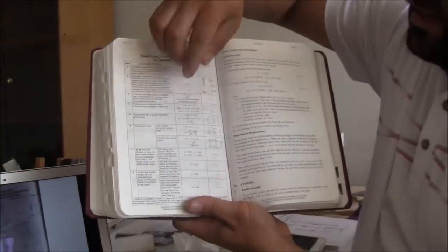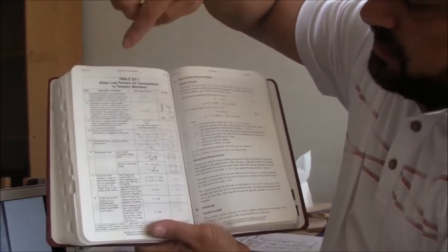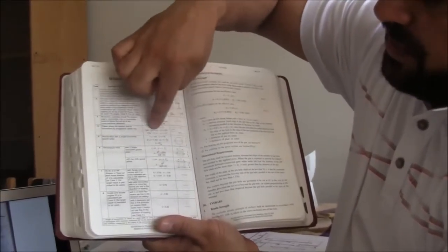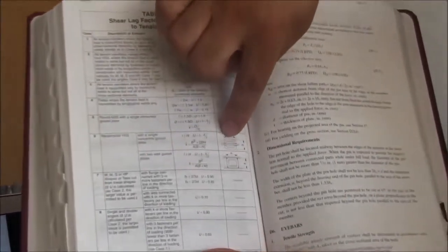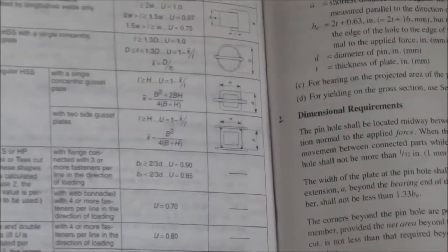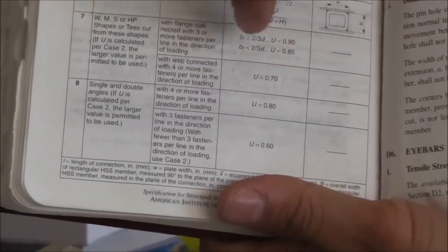This includes all the cases, and it includes cases for the welded connections. This is for the welded connections. And this is for the HSS cases, hollow steel section. It could be a rectangle, it could be a triangle, it could be circular, which is called pipe, because the connection to these members usually is unique. And this is for the angles here. And these are permissible values for the W, M, and S shapes. But the general formula is 1 minus x bar over L.